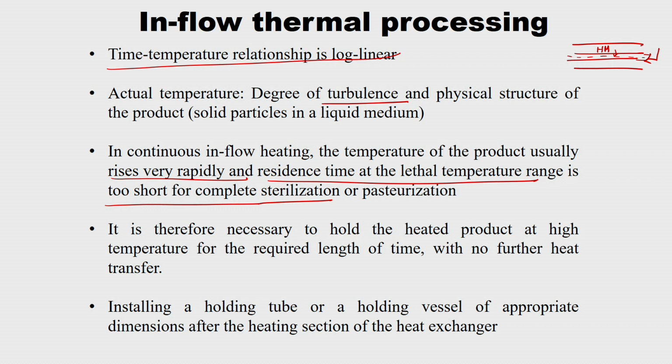So, to get the lethality range, I had to hold it for some time, right. So, the residence time at lethal temperature range is too short. So, I need to hold it, even though it has already reached the required temperature, for some time to get the required lethal range, lethality for any sterilization or pasteurization. So, that is where the concept of holding tube came in.